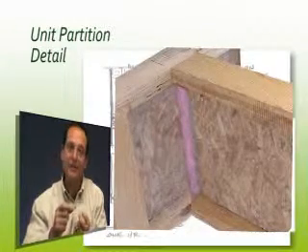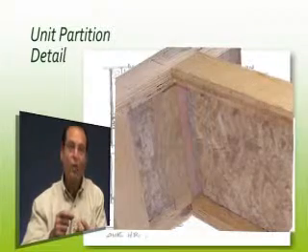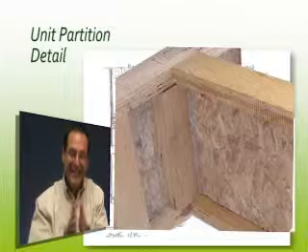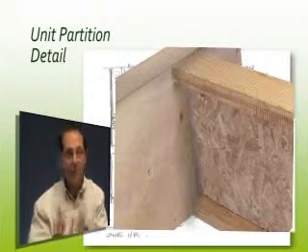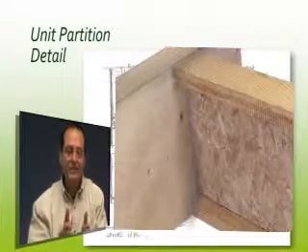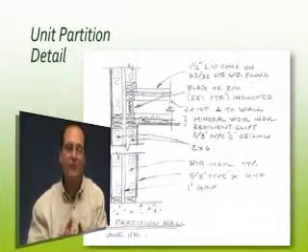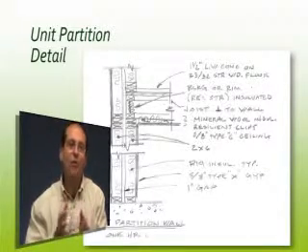Would that be considered adequate as fire blocking or draft stopping? Or should that in fact be a solid piece of wood? Should they put a piece of 1.5 inch rim at that spot too, so that you have a full 1 hour both sides? Again, this was the interpretation that was taken for this particular project. It may not be where you are.